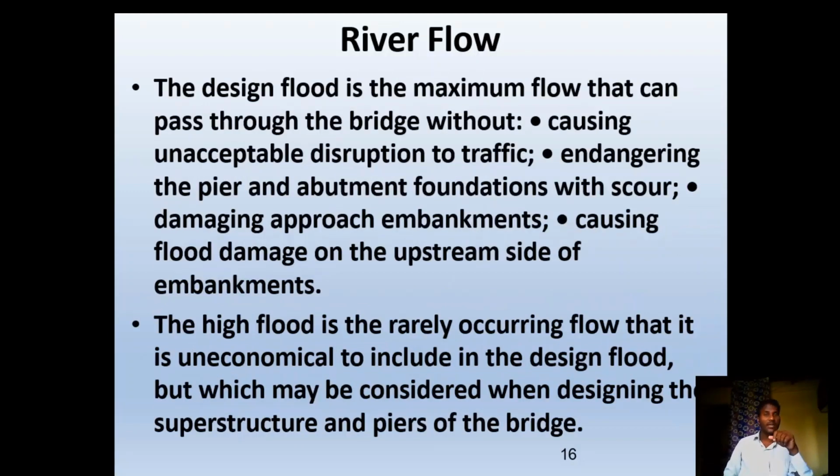The design flood is the maximum flow that can pass through the bridge without causing unacceptable disruption of traffic, endangering the pier and abutment foundations with scour, damaging approach embankments, causing flood damage on the upstream side of embankments.